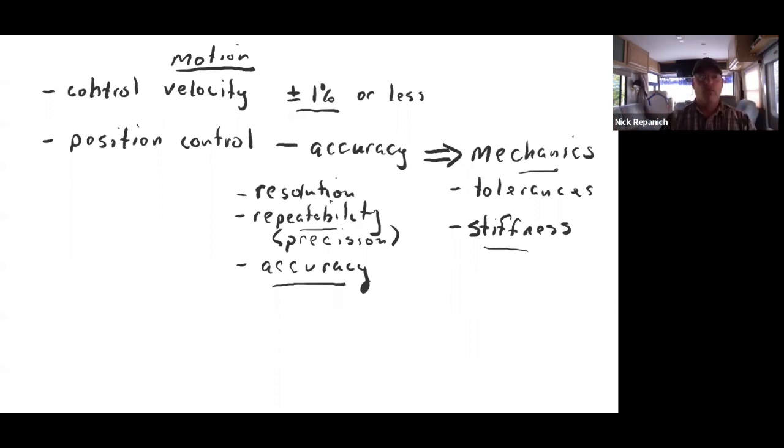What are the frequencies and the harmonics of it? And the hardest thing we have to do in designing motion control equipment is design in stiffness. It's fairly easy to get things that will move to a separate spot with exactly the same load or with very little friction, very little disturbances. But as soon as you start to deflect something with load, then it's a much more difficult design.